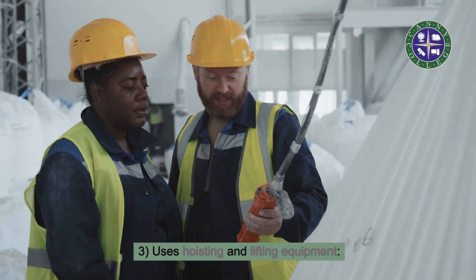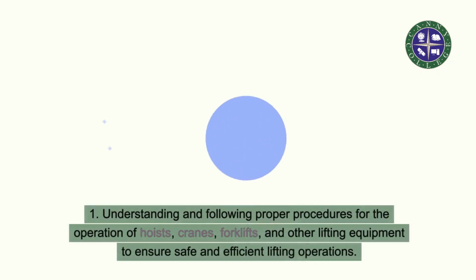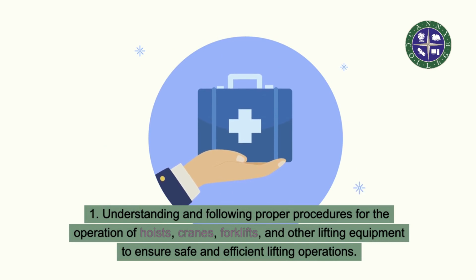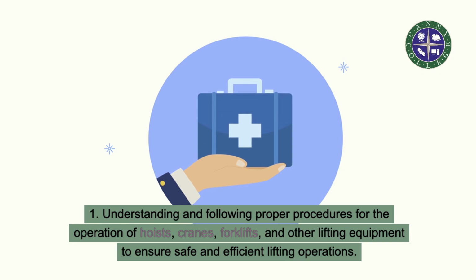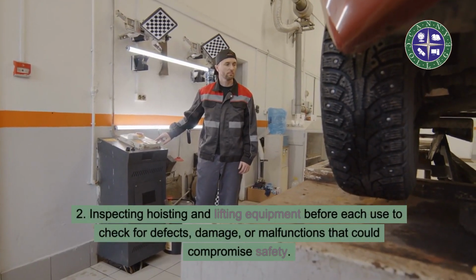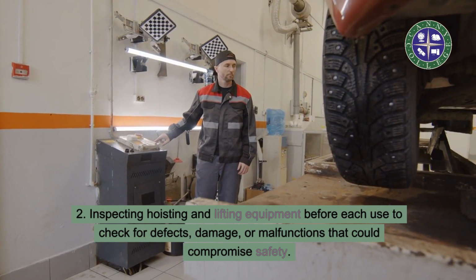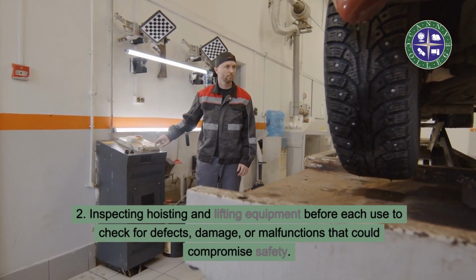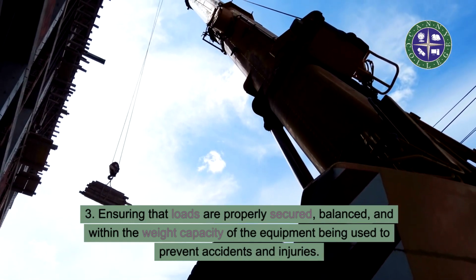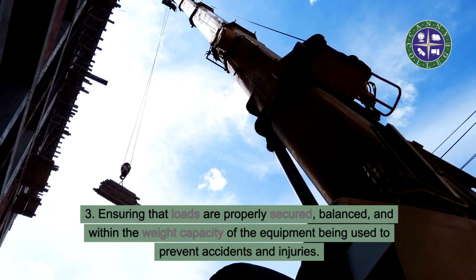3. Uses hoisting and lifting equipment. 1. Understanding and following proper procedures for the operation of hoists, cranes, forklifts, and other lifting equipment to ensure safe and efficient lifting operations. 2. Inspecting hoisting and lifting equipment before each use to check for defects, damage, or malfunctions that could compromise safety.